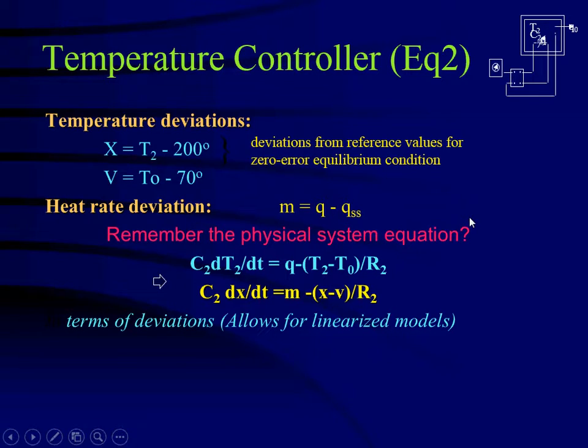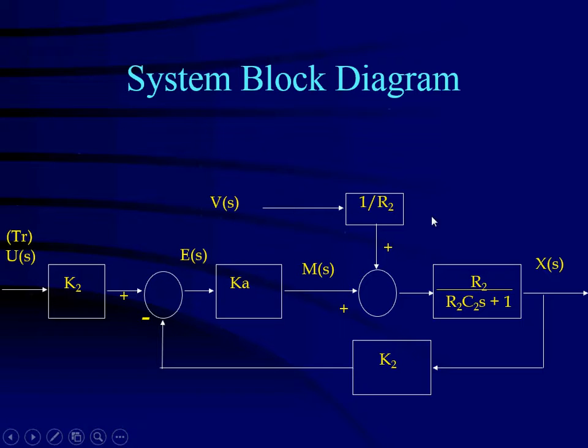So when you are designing a control system, like in my case, I will have to give you the conditions, what we want the control system to do. Because what's happening here is your plant, this is your physical system, is being modified by this other block. If between these two you have a transfer function, then the combination of the controller plus the system produces a different output, which is the one that you want for a control system.